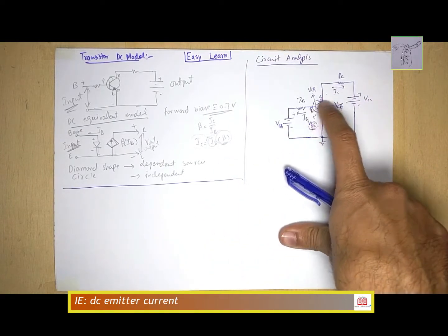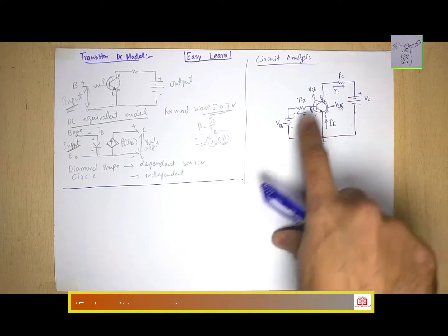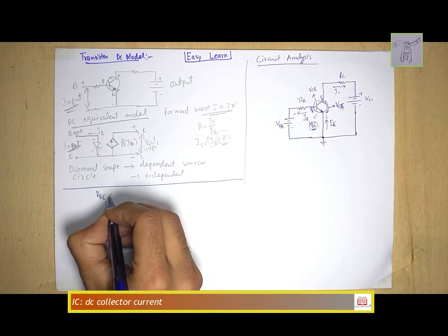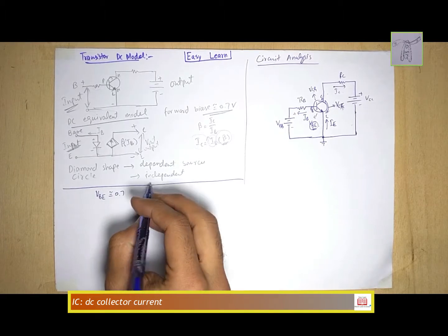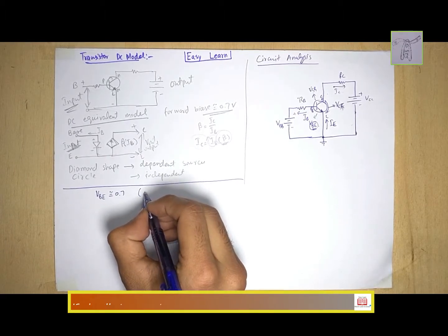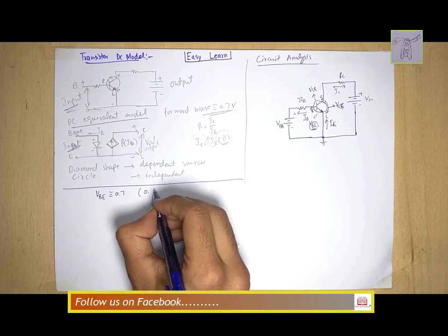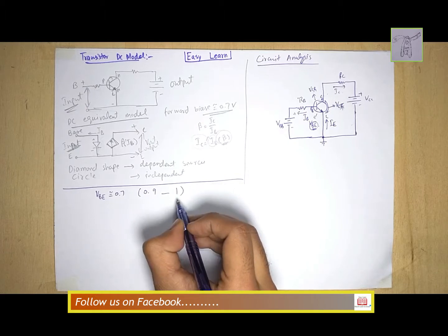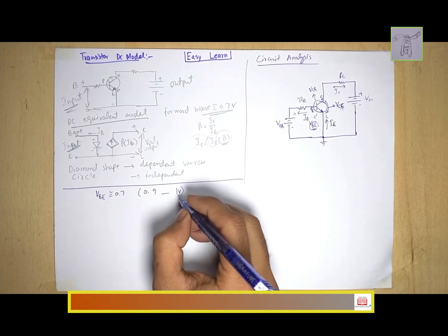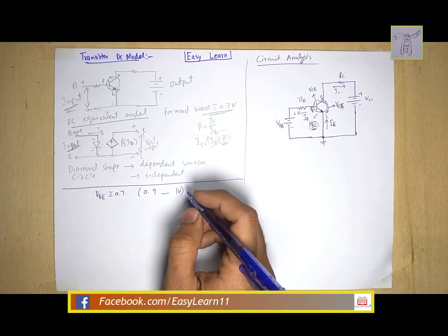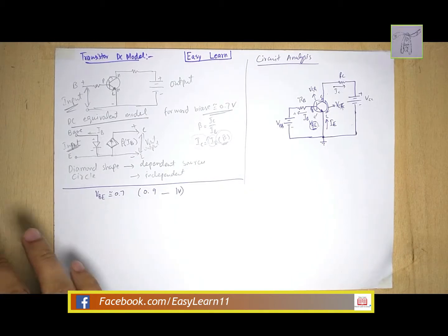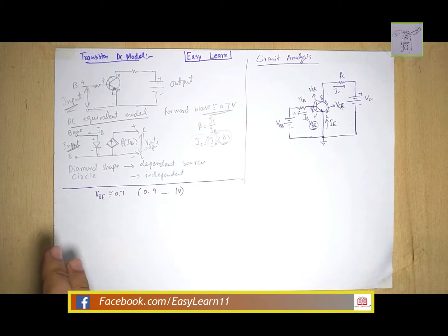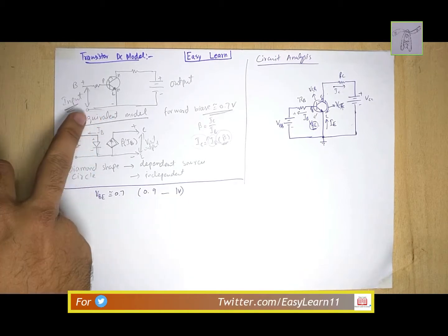When the base emitter region is forward biased, there is approximately a 0.7 volt drop. Understood? I know that in practical cases it can reach up to 0.9 and sometimes even 1 volt, but for easier understanding we will use 0.7 volt throughout this course, and it has a normal characteristic curve and all the parameters are just like a normal diode.